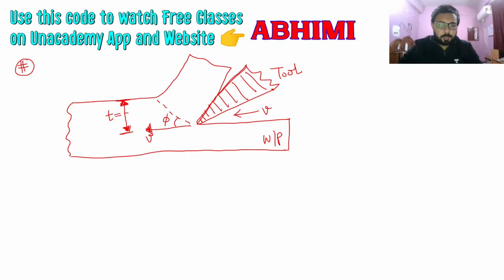And this right here is the thickness. Uncut chip thickness will be equal to the depth of cut. So this TS, the thickness or length of the shear plane, will be t by sine phi.